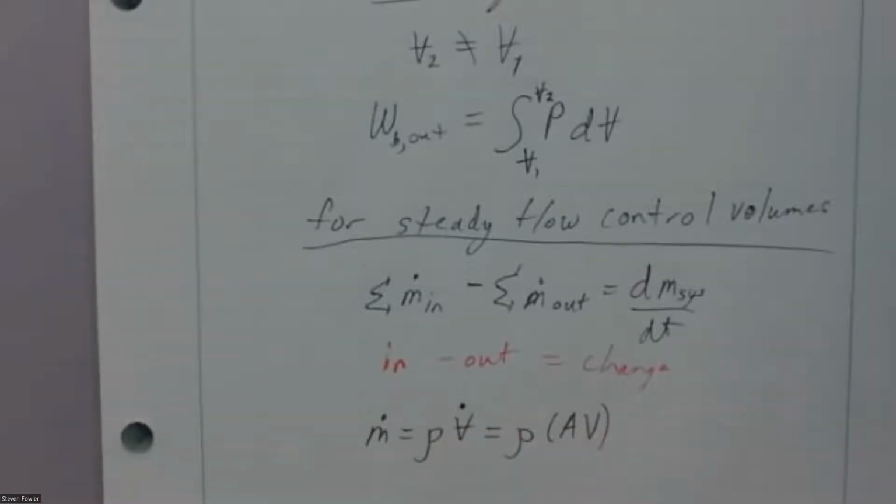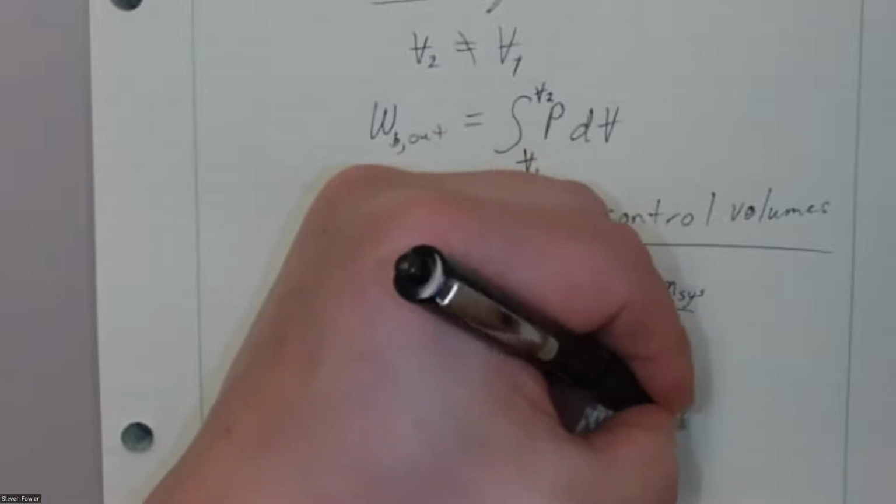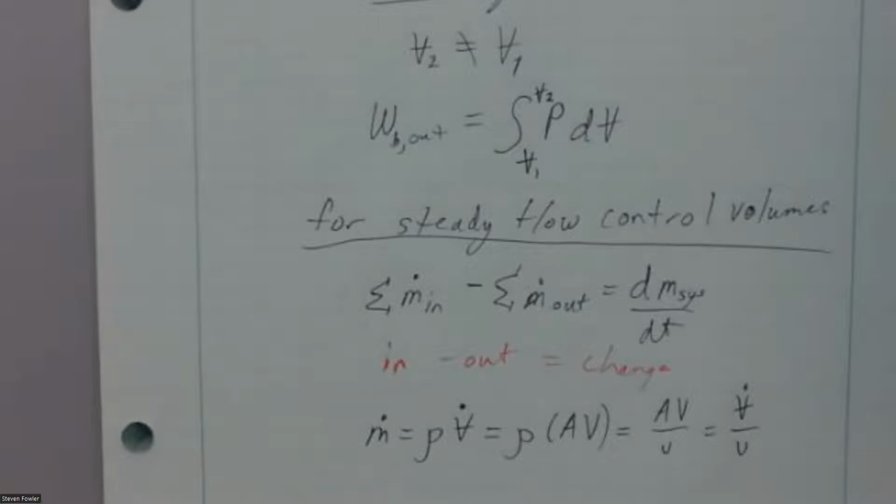That's volume per time. And again, we've defined throughout the semester that the reciprocal of density is what we call the specific volume. That's little v. So anywhere I've got density, I can plug in 1 over the specific volume, and that's the same thing. So again, as we've seen throughout the semester, know which v you're dealing with. Is it speed, volume, or specific volume? That's not changed. So this is how we would find the mass flow rate. There are a variety of ways I could find the mass flow rate, and everywhere mass comes in and everywhere mass goes out of my system.